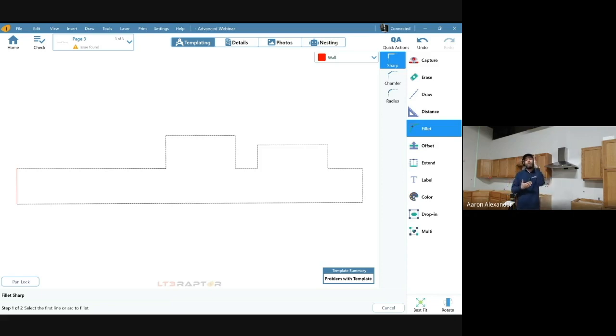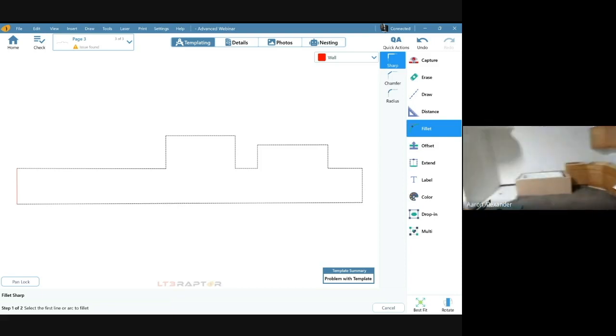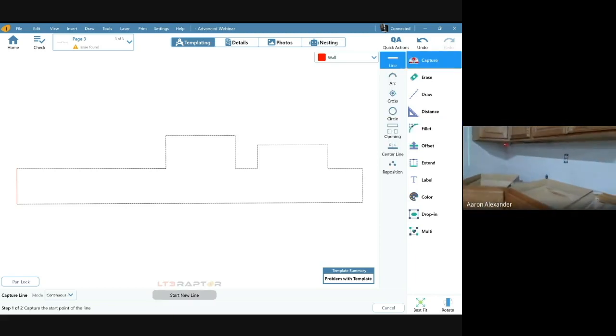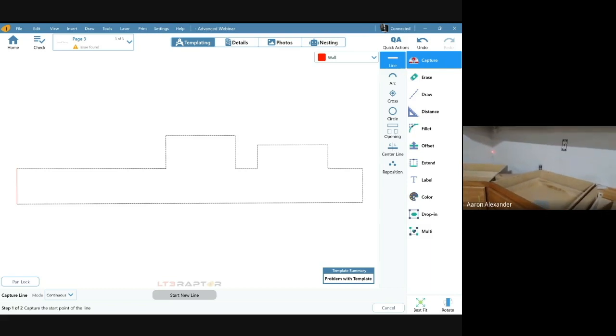Now, when we're dealing with a vertical situation here, the farther you come out of that corner, the less mud you're capturing when you shoot that point, okay? So what I mean by that is when we go to shoot this drywall corner here and create these points, if I'm right close to the corner like that, I'm getting the mud buildup that taper floated into there.